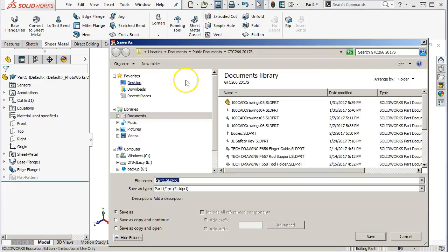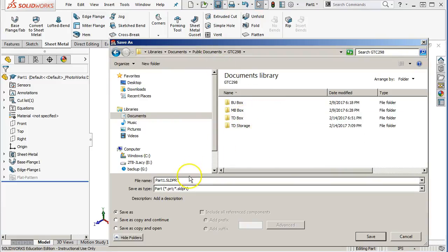All right, so let's go ahead and save this. It doesn't like the contours and regions. It's not a contour and region type deal, no. So if we need holes, if we need additional geometries in this sheet metal box, we're going to do it as separate features. We're not going to include it in the flange or in any of the specific commands.